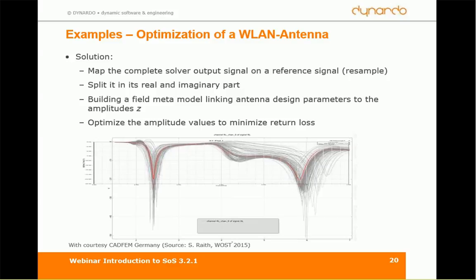Those already knowing some scalar software like optiSLang could point out that the parameterization task could also have been done manually at pre-selected abscissa points, as I also mentioned in my introduction. On the other hand, using Statistics on Structures, one does not need any a priori point, but can use the whole abscissa. And to be honest, which hotspot or even which group of points would you pre-select around the singularity at 2.4 GHz? It's simpler, less error-prone, and especially more accurate to use a random field model for this task.